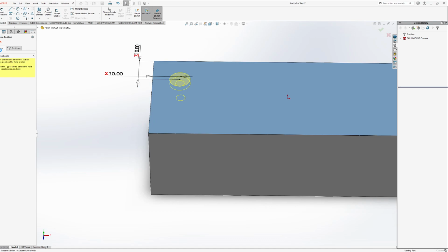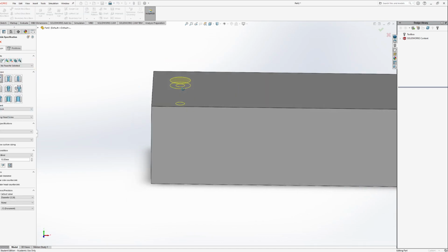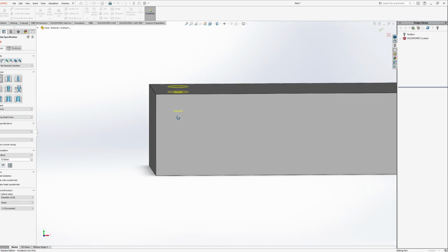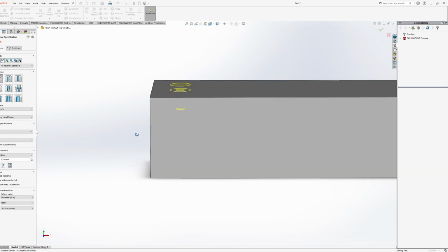And if I'm actually correct, I might have cheated here a little bit. Yeah, since I made this the other night, some of these measurements are already here. I'm sorry, I'm a cheater. But we have a C bore, or counterbore. It is a standard ANSI inch binding head screw, size is number 5. Fit is close, doesn't really matter. We're not too concerned about that unless we're actually applying screws. And it has a 10 millimeter depth, down to the tip.